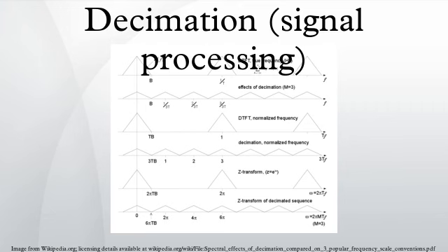By a rational factor, let M/L denote the decimation factor, where M and L are integers. Interpolate by a factor of L, decimate by a factor of M. Interpolation requires a low-pass filter after increasing the data rate, and decimation requires a low-pass filter before decimation. Therefore, both operations can be accomplished by a single filter with the lower of the two cutoff frequencies.